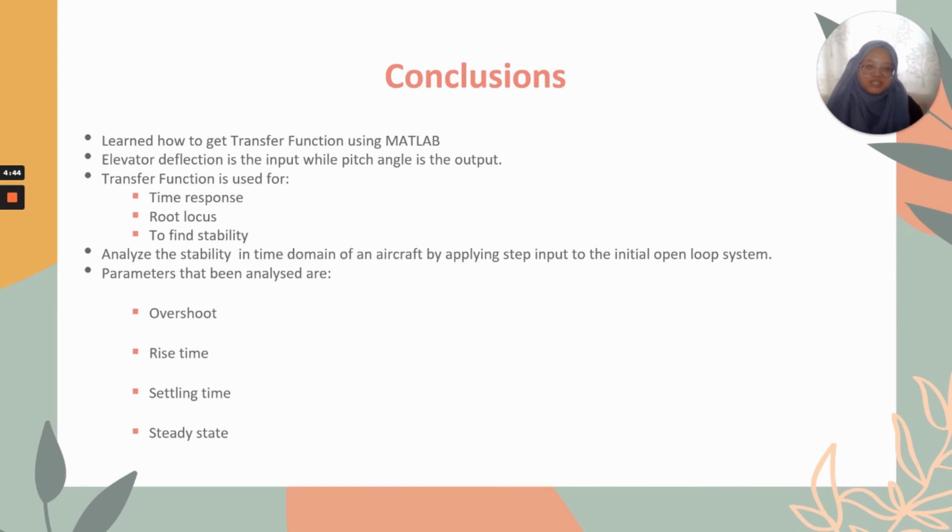As a conclusion, we learned how to calculate the transfer function using the Matlab software. Our project is related to the pitch angle of an aircraft. So we conclude that the elevator deflection is the input while the pitch angle is the output. From the transfer function we use it for time response, root locus, and to find the stability of the system.